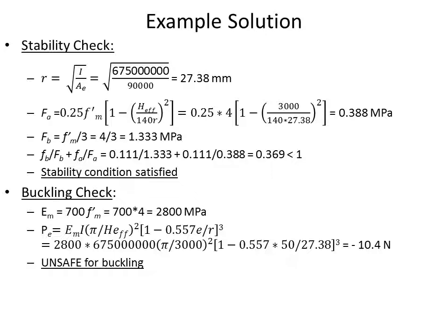And if we think about it, why is that happening? Of course, it will happen because you are having a 4-meter high wall without even a lintel in between. A lintel is what we call in Arabic ataba. So you have something very high without anything to support it in the lateral direction.